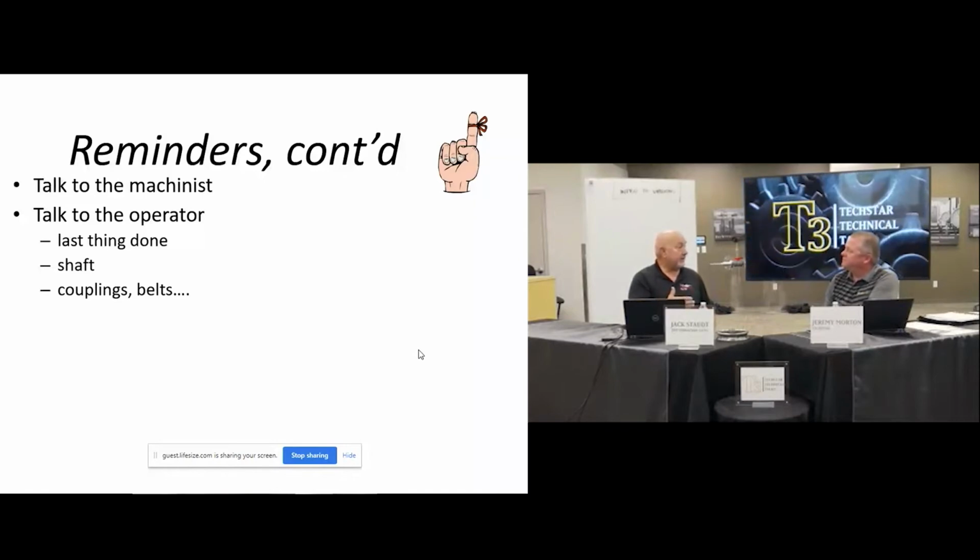They didn't allow the flexibility for the mag center, so they actually had it pulled to one side. The motor was fighting to get into its mag center. Absolutely. Okay, interesting. So be prepared, if something's not broken and you fix it, be prepared to fix it again. Yeah.